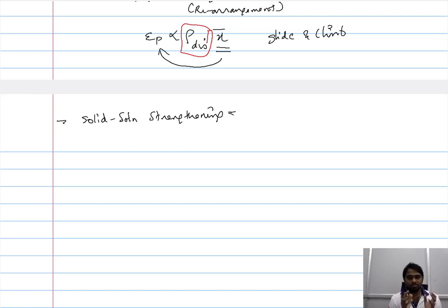So when you talk about the solubility of the solute, you have to go back to a law that governs the solubility, which I guess by now you would have guessed. This is the Hume-Rothery law. This law dictates what are the factors that govern the solubility of the solute that you add to the solvent, that is the base metal. So when you add an alloying element to a base metal, the solubility is governed by several factors, and these Hume-Rothery rules compile all these factors. And one of the factors is the difference in the atomic size.